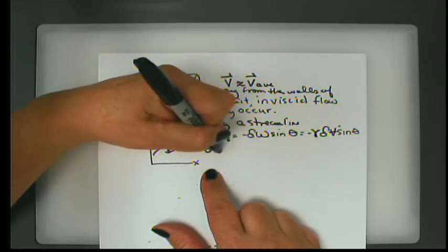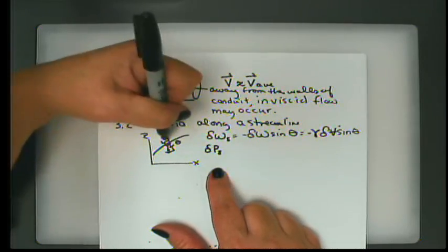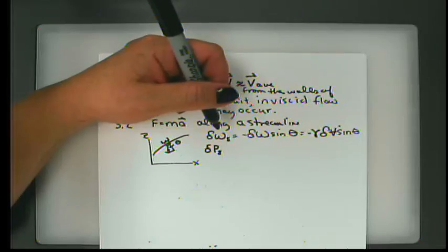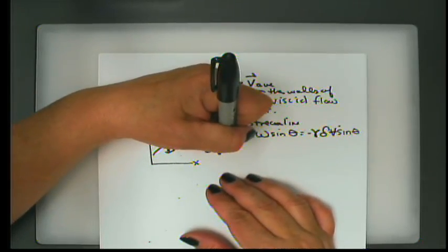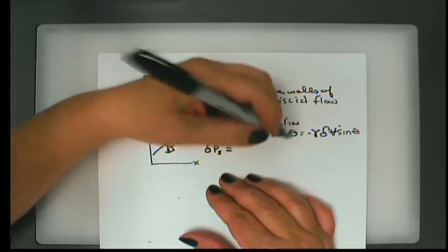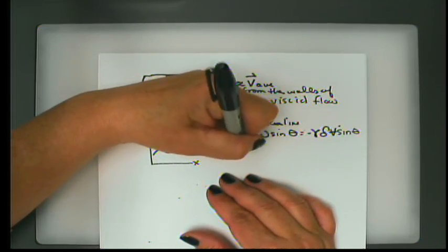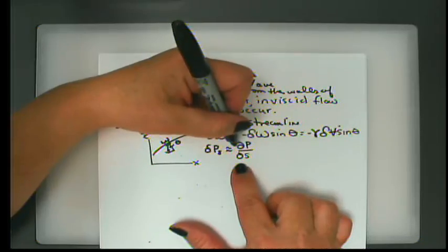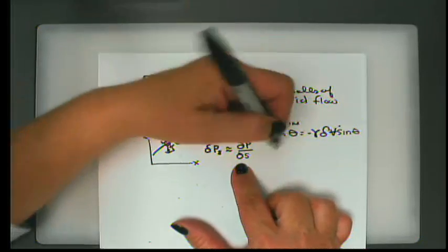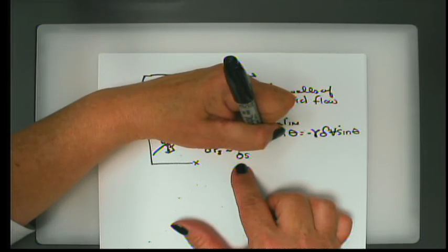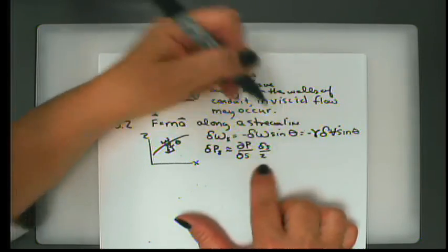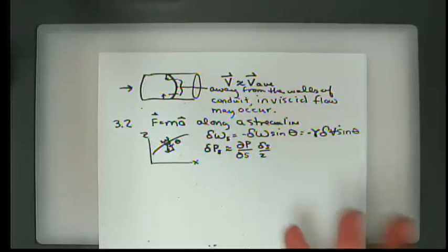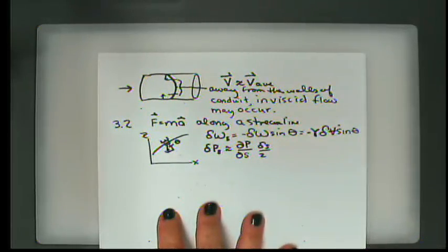and we can think about that as being along a streamline, as being, if there's a difference in pressure from here to here, and this is the center, we can sort of approximate that by a one-term Taylor expansion. And we did this back in chapter 1 also. We didn't really talk too much about it. But we can say that it's equal to dP/dS, which would be the pressure gradient along the streamline, times del S over 2. All right? And you can think of that as being in the middle, averaging in the middle, or you can think of it as a first-term Taylor expansion.